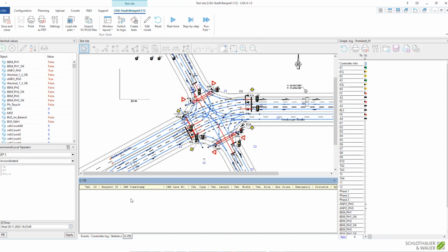These messages are not all directed towards this intersection. They are usually meant for a certain intersection, be it the intersection the current vehicle is approaching and is matched to the map, or, if it's a request message, an SRM, a message specifically for one intersection. But of course, the RSU will first receive all of these messages and has to filter them in a certain way. The result of this filter is what we call the vehicle buffer, which shows all the messages that are relevant for the current intersection.